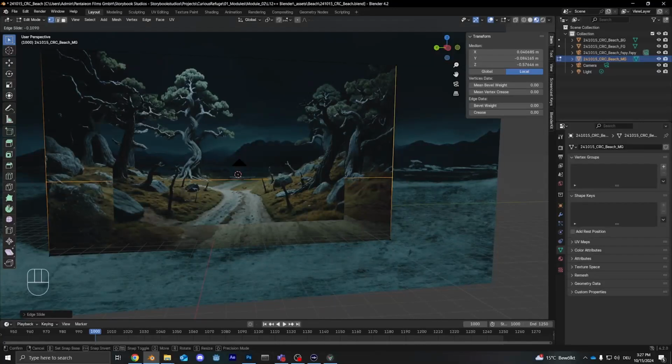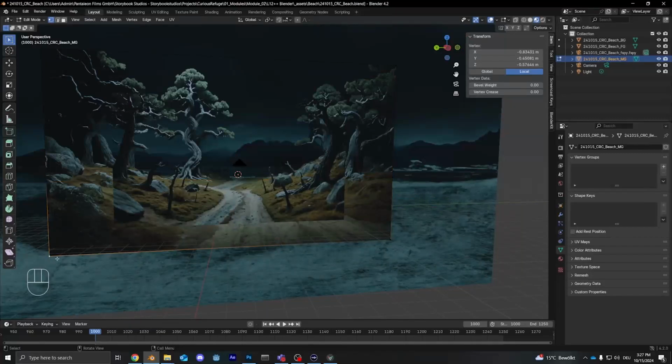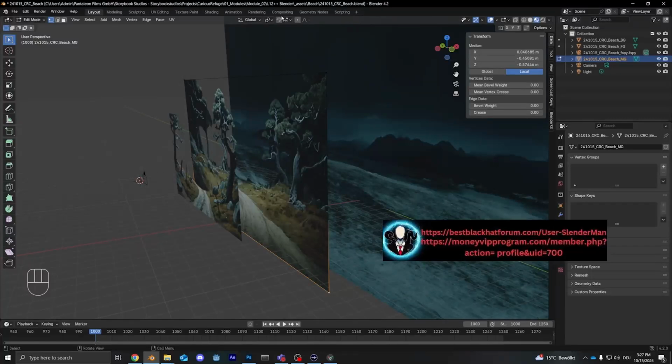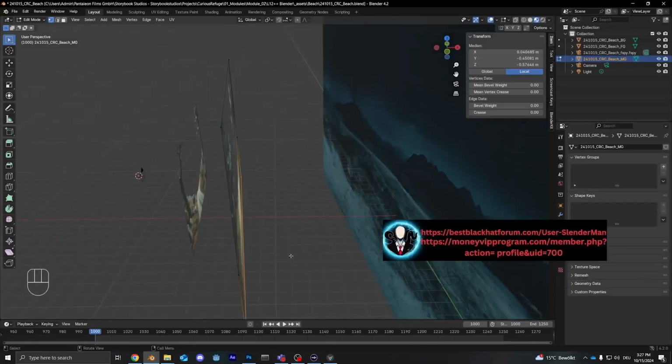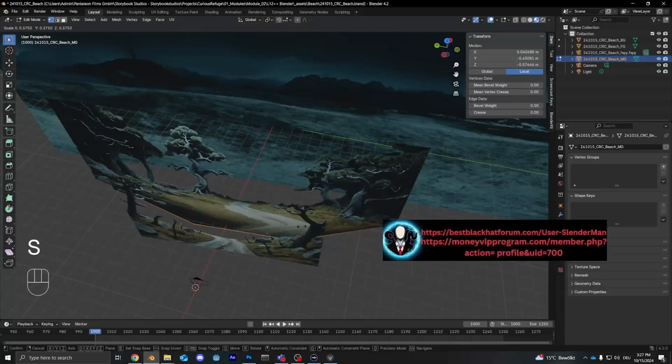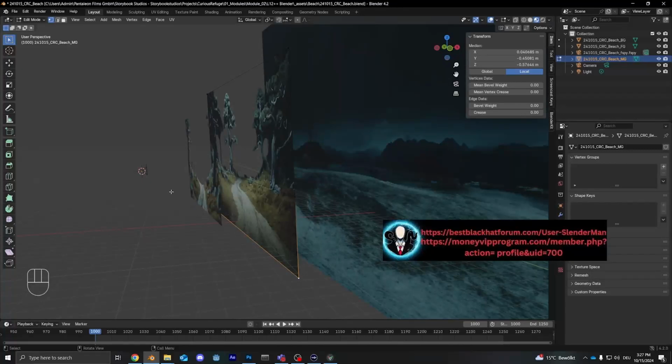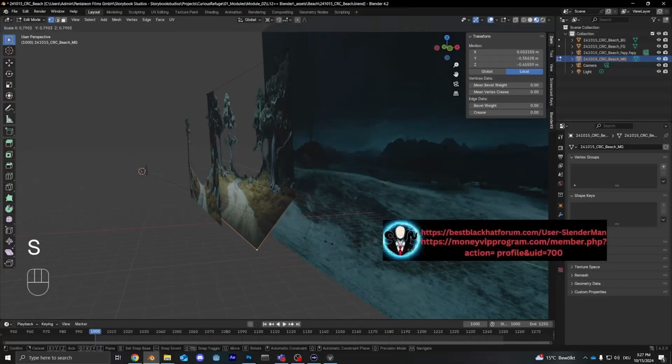And I'm going to put it up here so we can move this entire portion down here closer to the front. And to do so, you just need to select these bottom vertices here with Shift. And now we are going to change this setting up here. So usually the pivot point is between just kind of the center of what you have selected. So if we hit scale, it's going to scale towards each other. We don't want that in this case. We want to actually scale this towards the camera so we don't see much warping in our camera image. And for that, we change it to 3D cursor because we still have a cursor on the camera. So now if we scale, it's going to move up toward the camera.